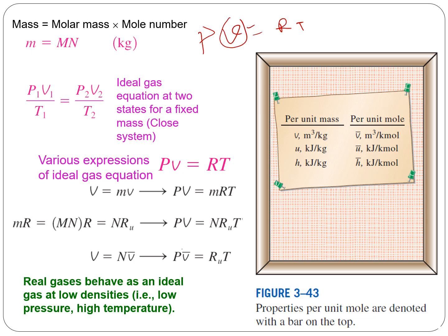Okay, the basic formula for ideal gas is Pv equals RT. So this is specific volume. Specific volume is volume per unit mass, so you can also write PV, which is volume, equals mass times RT, and mass can be molar mass multiplied by the number of moles. This is another way of finding it. Sometimes you may have to use this equation if you are working in terms of number of moles. Here this is the universal gas constant.